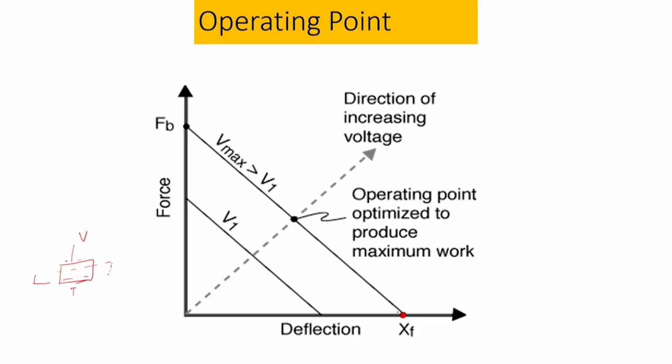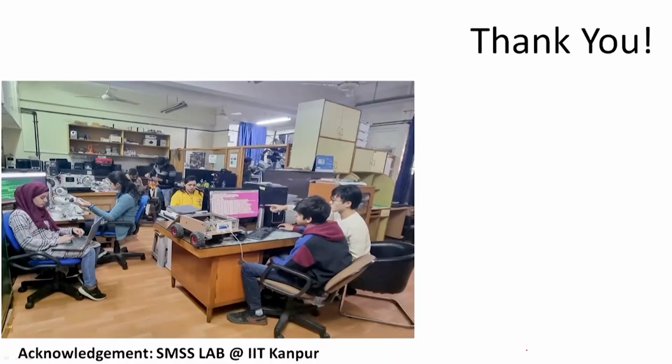Now, imagine that I am not allowing it, I am putting some walls that stop it from expansion, but it wants to expand. So, it is going to create a force. So, this is what is the blocking force. Now, in reality, all piezoelectric material is in between this displacement and the blocking force, somewhere here, some amount of force, some amount of strain, and we have to design always where will be this operating point. That is part of the design activity. Thank you very much.